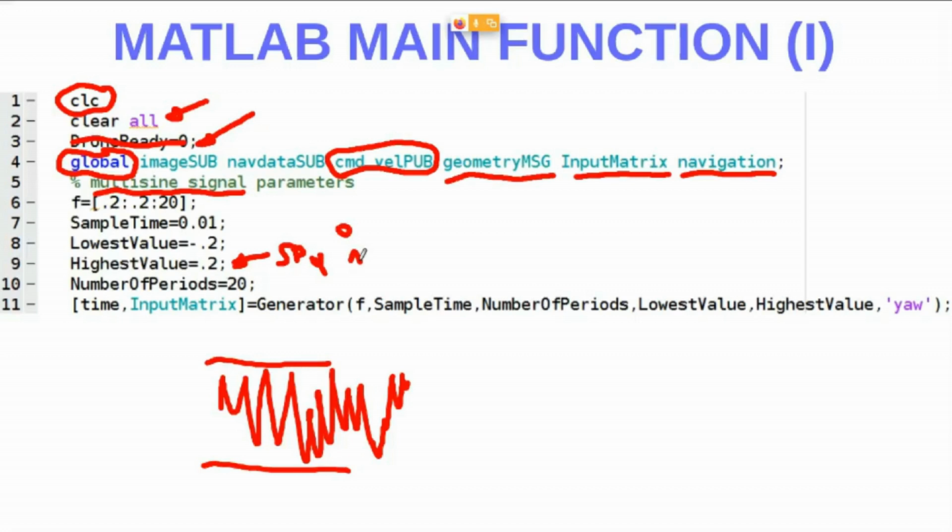That's the important thing. So it's not in degrees or radians, it's normalized between 0 and 1. So I have chosen 0.2, as you will see later, in order for the aircraft not to move so fast all along or all across the laboratory.